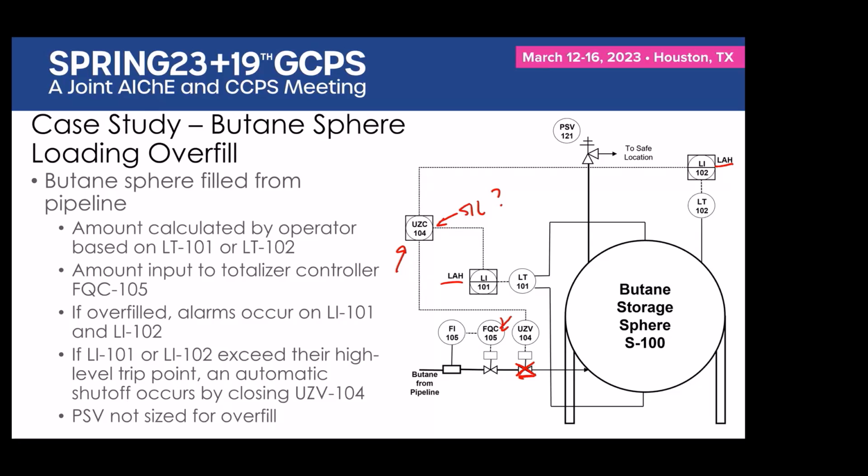They need to determine what response action they need to take in response to that, and then they need to go perform the action. If the operator has sufficient time and the other criteria are met, that gets a 0.1 probability of failure. That's the traditional operator response in a LOPA that gets a 0.1.